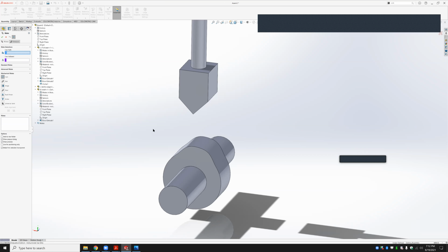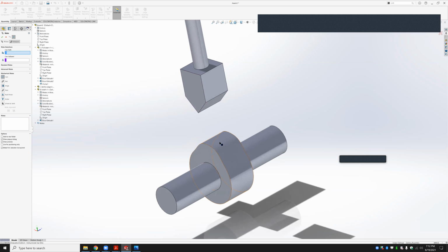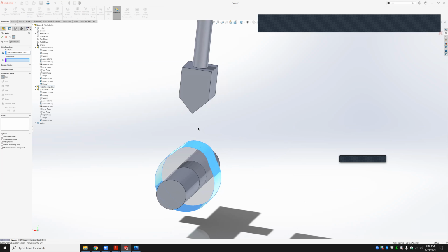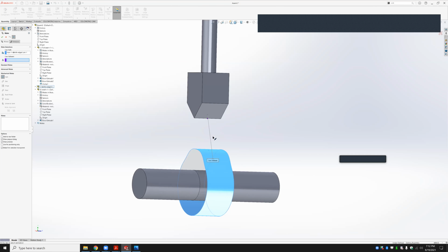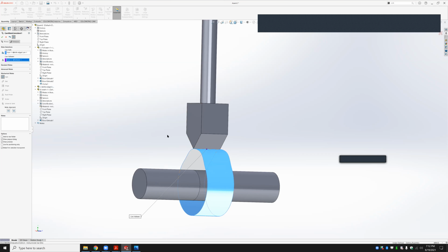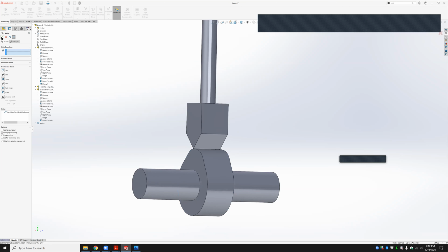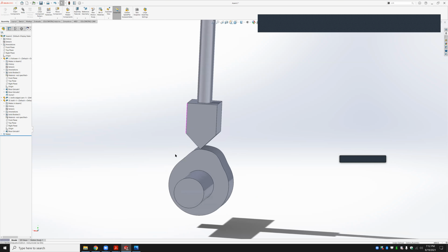See it right here. So the cam path is this smooth surface right here. It used to be the case that the path had to be a single curved surface, or just a single surface, I'll say. I don't think that's still the case. It may be, but either way, we have a single smooth surface right here, so we're good to go. And then for the cam follower, you can just pick that point right there on that edge. And then that should be everything that you need to finish your cam assembly.